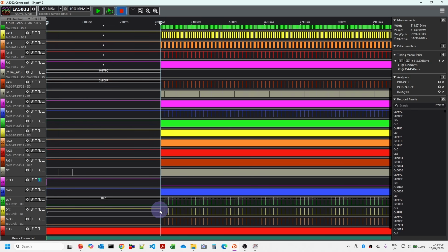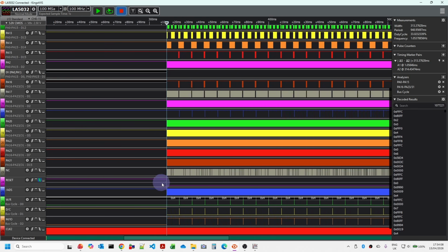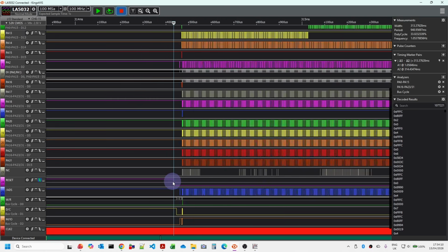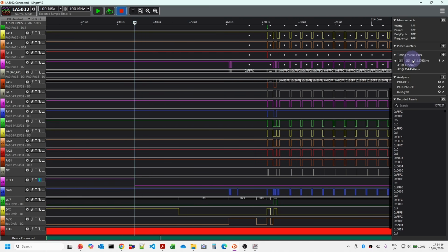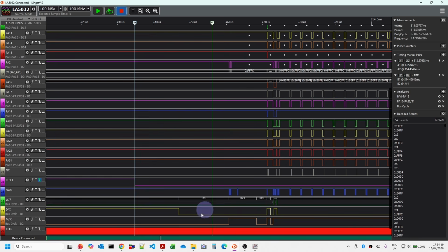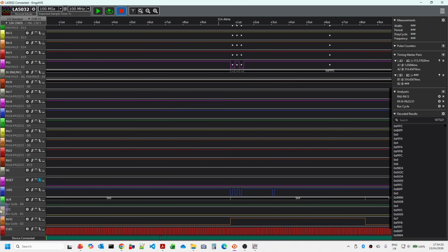And then we can see here that when reset finishes, we should then see some activity. So if I just put some more timing markers here. When reset finishes, the first activity is when you see the address strobe here. Address strobe indicates there's a valid address on the address bus, so that's really the first time that we get anything valid.